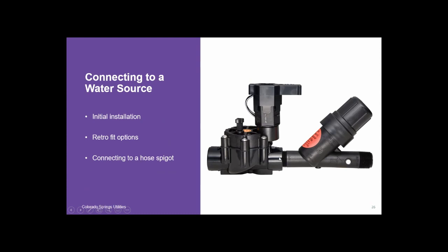So that's going to come directly out of the valve, and then we'll have a fitting here that is threaded that connects to our, whether we're using a 1/2-inch or 3/4-inch drip pipe, and that will start to make its way onto the top of the surface. So this might be found in a valve box or a manifold.